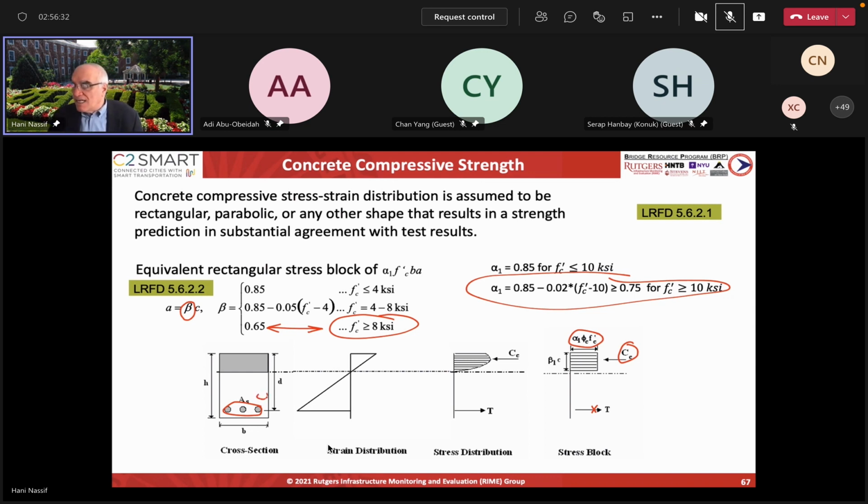However, if I add another area here, APS, then you have another T coming from the pre-stressing, which is equal to APS. In this case, I have T, initially it's AS times FS, the stress in the steel. And usually at ultimate, we assume that by the time this reinforced concrete is going to fail, the concrete will crush and reach 0.003, this thing here will have reached yielding. So it's equal to Fy. So I can use this AS Fy normally at ultimate.